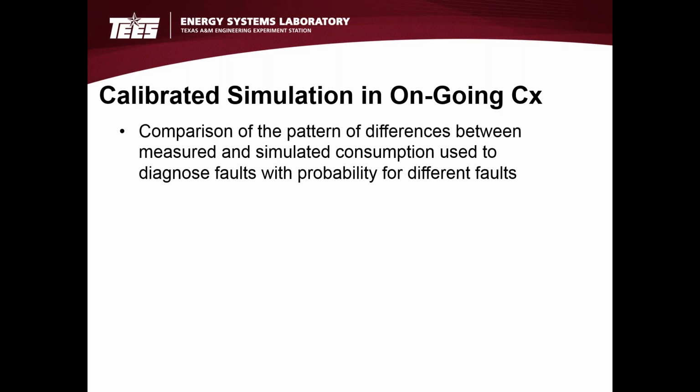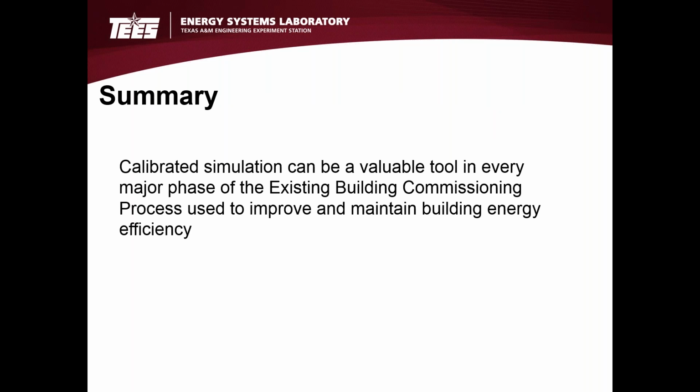And we have also gone on, and I've had a student do work that has come up with a very specific procedure for looking at the patterns in the differences between the calibrated simulation and the measured consumption, and then assigning probabilities to a variety of faults. So when you have no more information than the energy consumption from the building and the basic set points in the building in a calibrated simulation, you can get an approximate idea of what the probable cause of the deviation is.